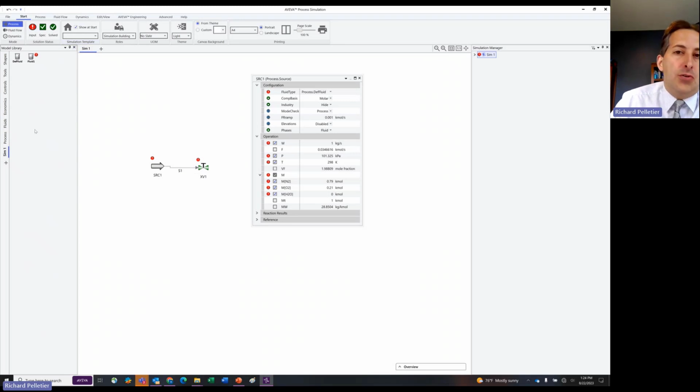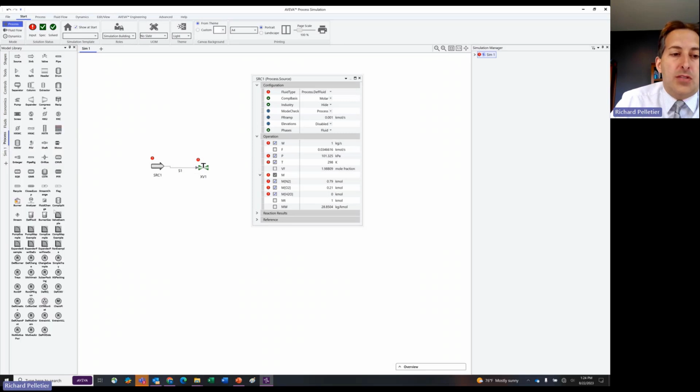And it's a place for you to put all of your custom models that you plan on using within that simulation. Your custom models can be everything from fluids that you have to create so that you can use them in your files, performance curves that get used in pumps or compressors, valves, etc. Or they could be customizations of equipment models or submodels that you are using to help build out your flowsheet, right?